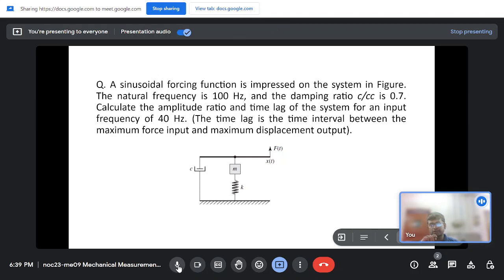Let me explain the system again, how it's working. We have a second order system with a lever. One end of the lever is attached to a damper with damping coefficient C, and the center is connected to a mass which is connected to a spring.